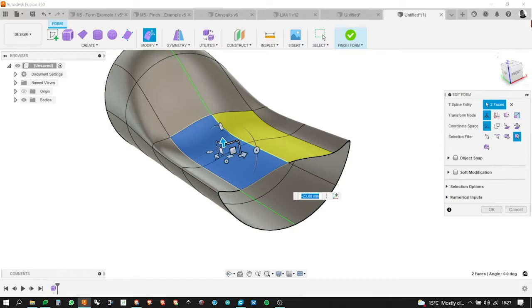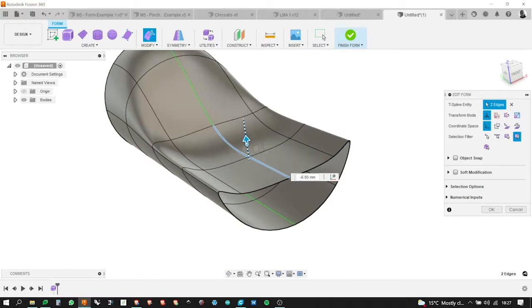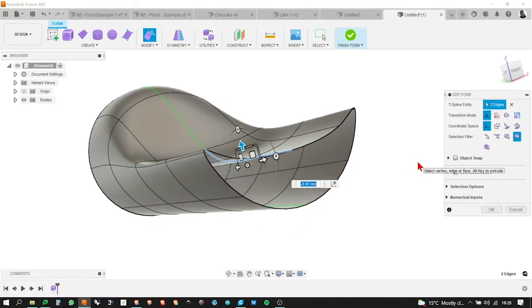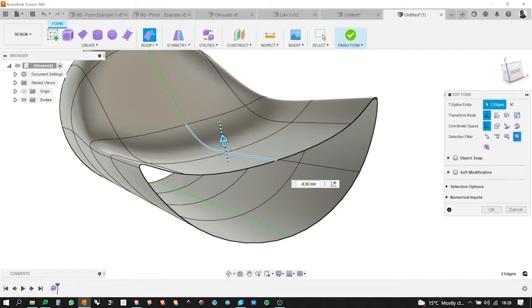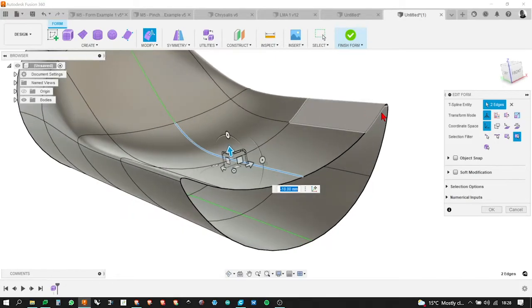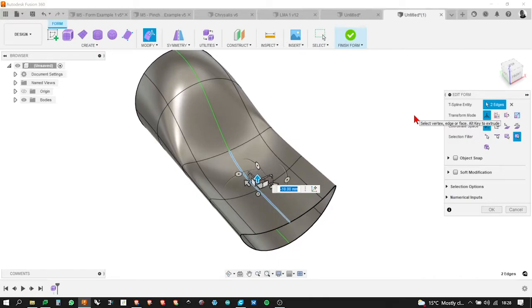At the moment we've got a shape which is doing this. I want this nice sort of smooth curve shape. So if I select these 2 lines here and pull those down to something that's a relatively smooth curve. We can't obviously be particularly accurate in this environment, but we can get something that looks like a smooth curve. So we're beginning to get that sort of top shovel shape. Now we need to bring the bottom of that shape up closer to it.